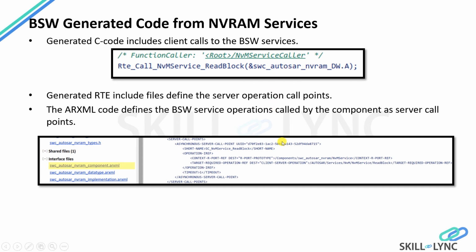And correspondingly for my ARXML also, if you can see, for all my imports, outputs that I am using, there are two imports and two outputs used. For both of them, it will be taken care of here. And apart from that, for my NVM service, that is read block over here, how it is defined and how the service call is taken care of with respect to my ARXML. So all that information will be given. So when you are even trying to import this ARXML, automatically my Autosar related information, their data type and any other information if it is there, will be worked upon over here.